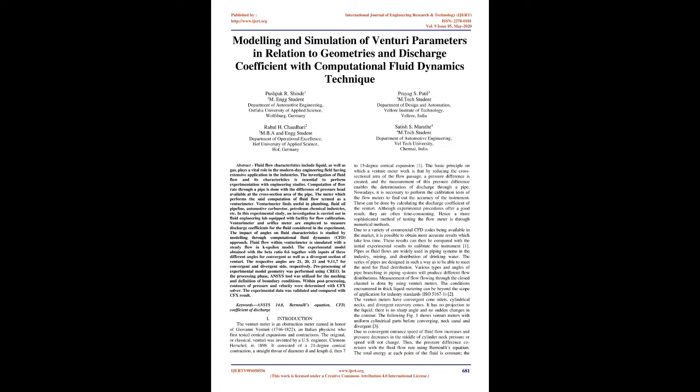Pre-processing of the experimental model geometry was performed using CREO. In the processing phase, the ANSYS tool was utilized for the meshing and definition of boundary conditions. Within post-processing, contours of pressure and velocity were determined with the CFX solver. The experimental data was validated and compared with the CFX result. Keywords: ANSYS 14.0, Bernoulli's equation, CFD, coefficient of discharge.